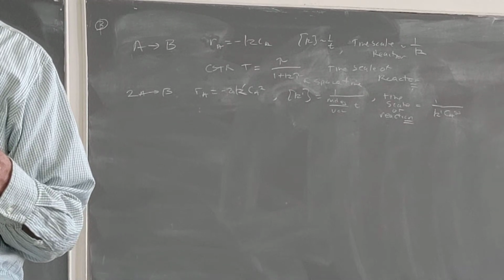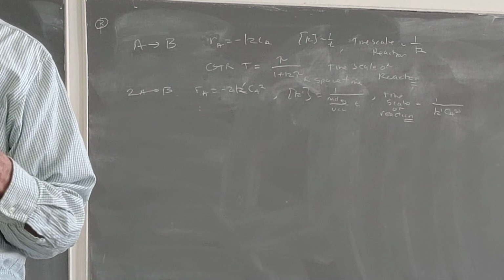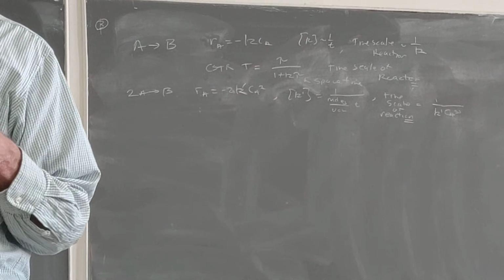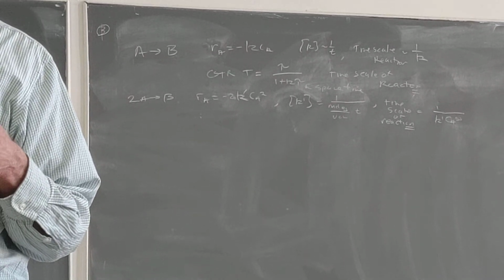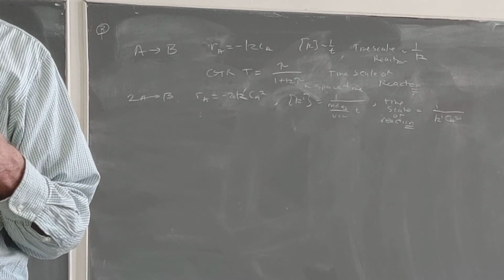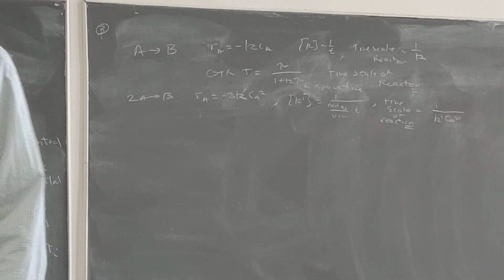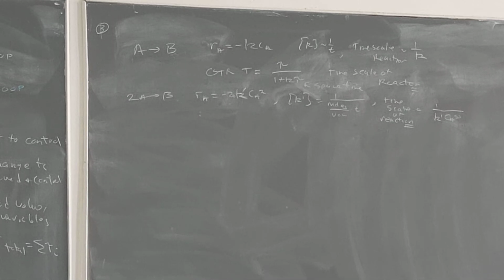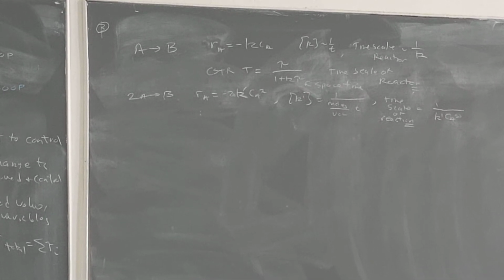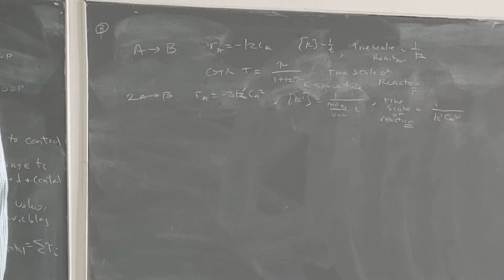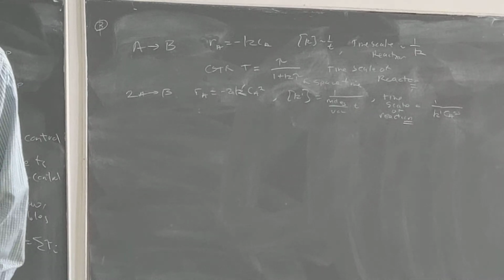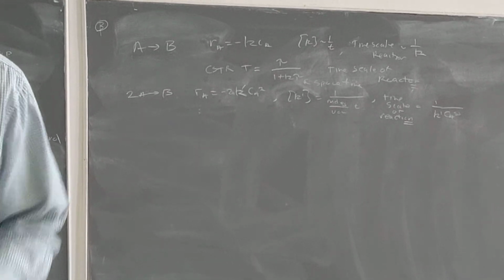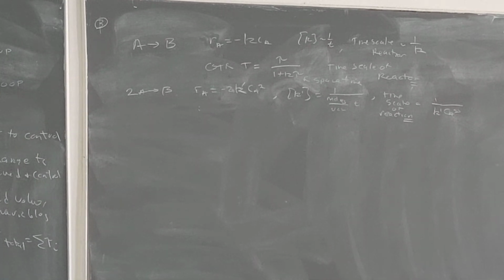The manipulated variables have a strong effect on the control variable that's relatively fast. And you also don't want the change in the manipulated variable to affect everything in the plant. You want it to be a localized effect on the control variable.